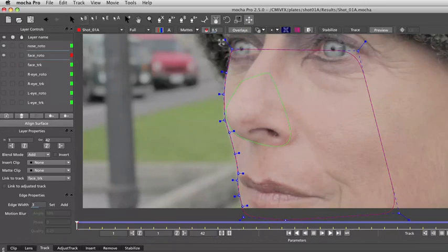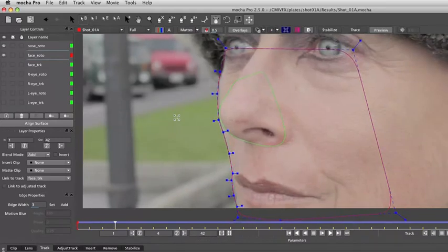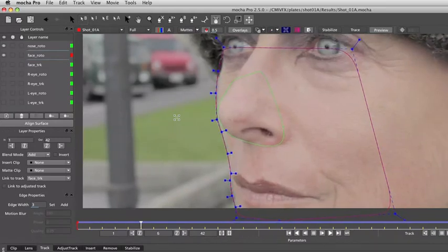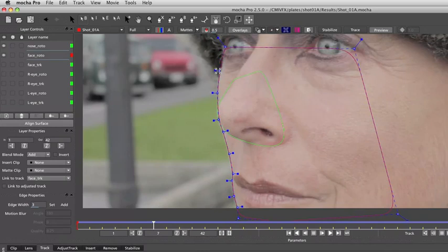I will turn on the Translate tool, and using the left and right arrows on the keyboard, I will advance some frames and choose the best timeline position to create my first keyframe. Try to identify a place where the movement direction changes, and this will be a good spot to adjust your shape. I will do the first adjustment here on frame 7. You can see that the Translate tool will move all the points at the same time.